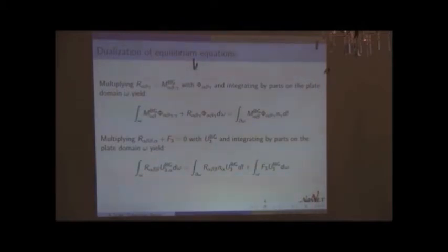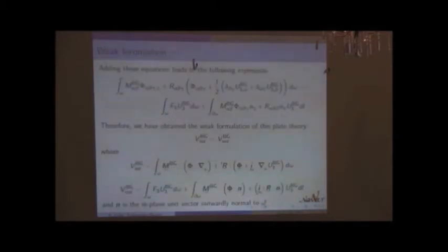All right, so I'm just summing those equations, doing the classical machinery of the principle of virtual work. I sum the relations, this is with full index notation. I have the internal power of the bending moment times what will become the curvature.